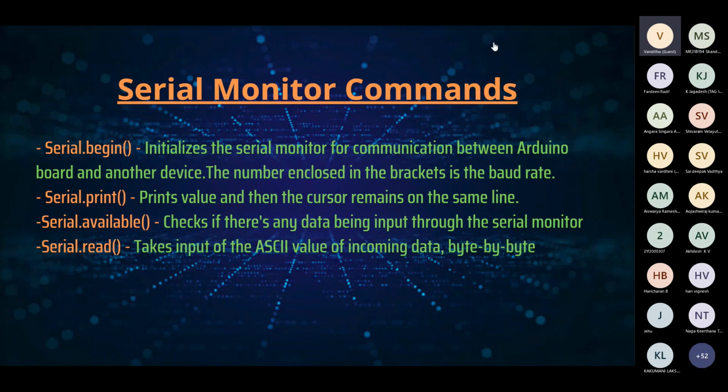Yes. As Roshan rightly points out, it's a fancier name given to the rate at which data is being transmitted through the serial port, in bits per second. And the default value of this baud rate is 9600, which basically means 1200 bytes per second.